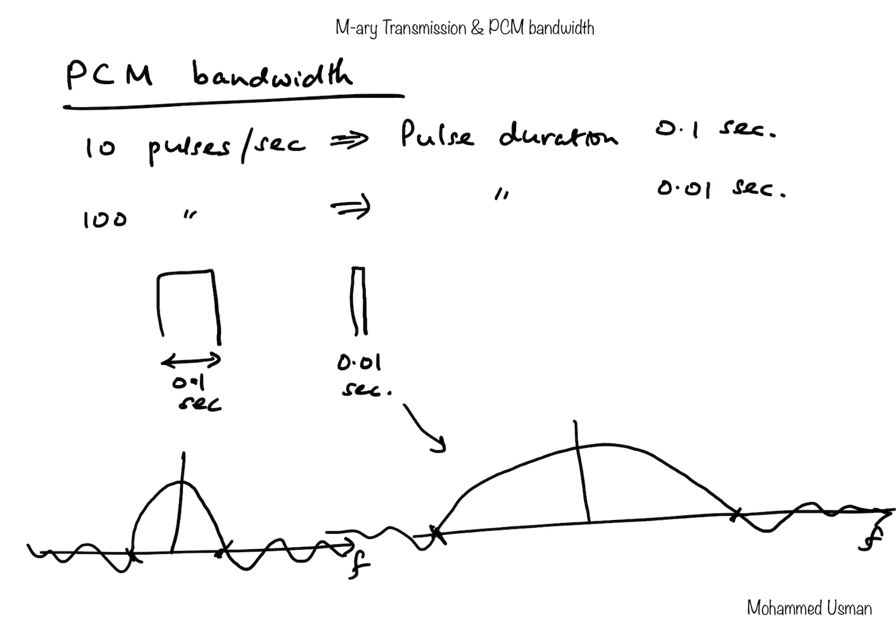When we're using rectangular pulses like these, in practice however we never use rectangular pulses because it requires infinite bandwidth, because you see these tails, they continue till infinity, even though they become smaller and smaller as you go further away, but theoretically it requires infinite bandwidth. But when we are using rectangular pulses, the minimum bandwidth required, in terms of the baud rate, can be written as Rs by 2.